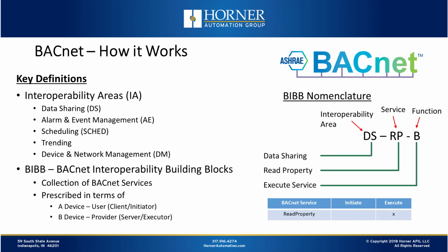Now, when you talk about interoperability between devices, we talked about the fact that they classify devices into different categories, and how those categories are really specified is through a couple more concepts that we have to review. First, called interoperability areas, the areas of sharing data between devices: alarm and event management, scheduling, trending, device and network management. Those, again, are 5 interoperability areas.